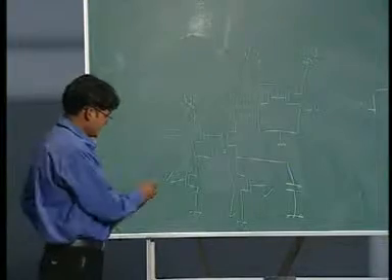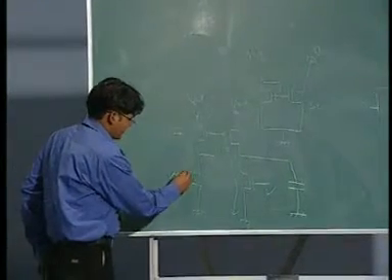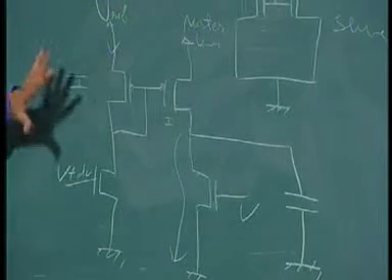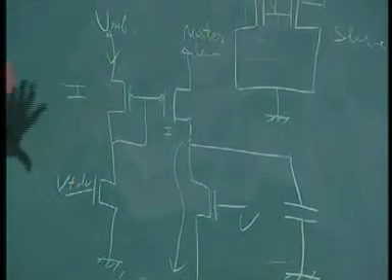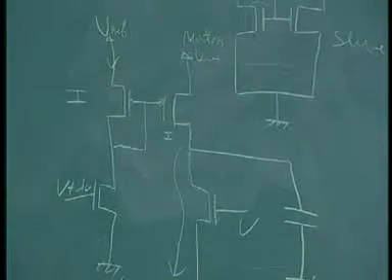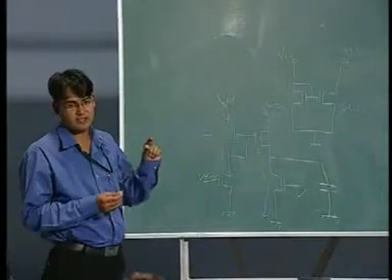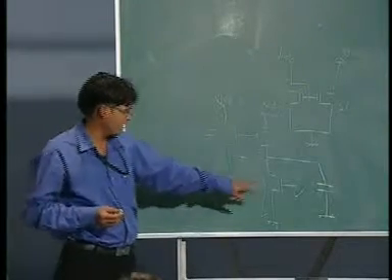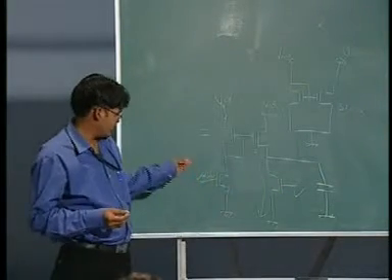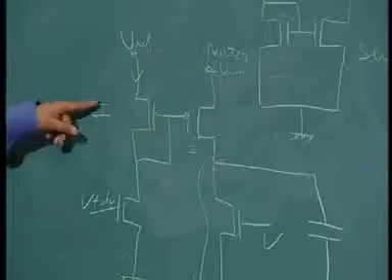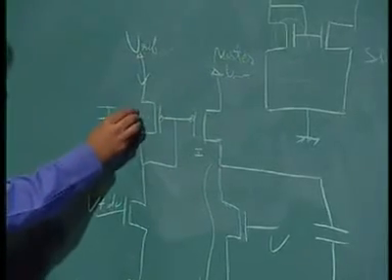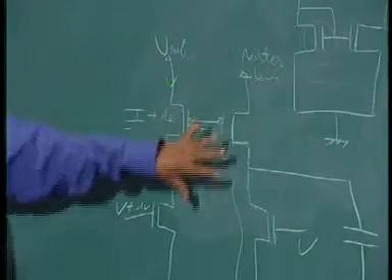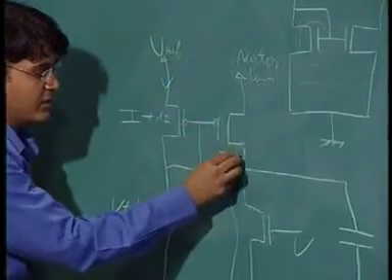But suppose I just increase the voltage to V plus dV. The principle of this differential amplifier is that it will amplify the difference. Okay. I have applied V plus dV here and here only V. So, the difference is dV. So, now my current will be I plus dI. Okay. The same current will be copied here, I plus dI.